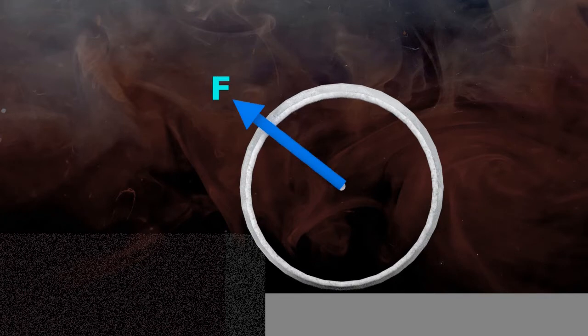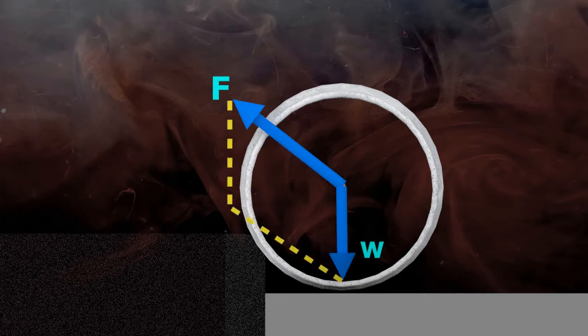Suppose there is no footpath and pipe is just lying on pavement. If force F is applied and pipe is lifted, only two forces will be there, force F and self-weight W. So if resultant force of these two forces is to be found out, according to the law of parallelogram, the resultant force Rf is the diagonal passing through the intersection point.